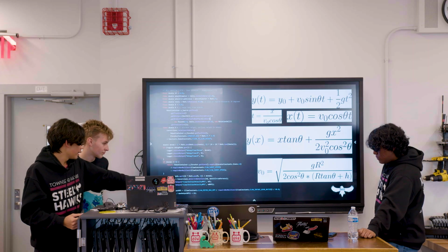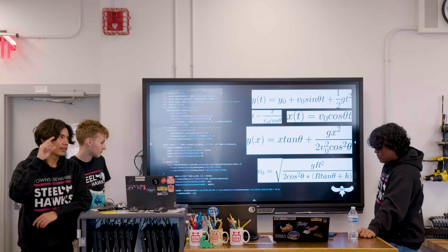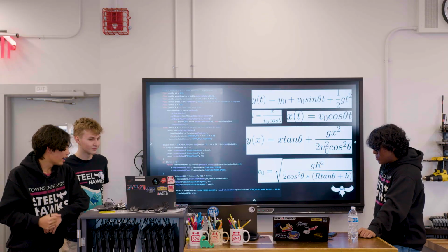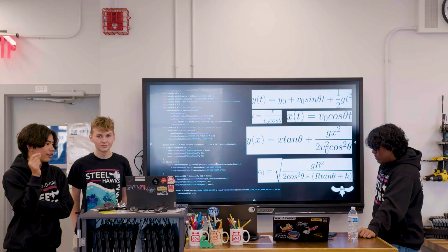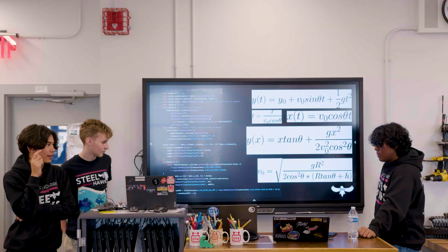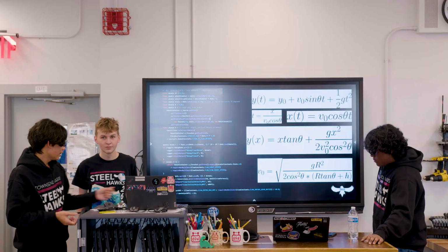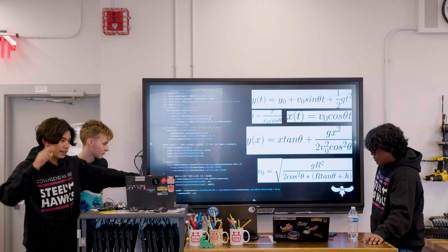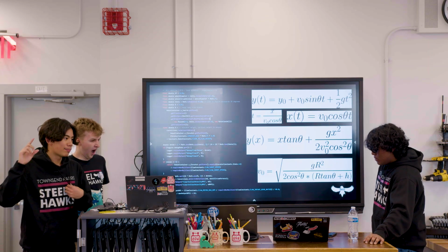And then we log it, and then after that we have the max rotations per second that our claw can move at. And we do this by finding the max RPM of our motor, dividing it by our gear ratio, and then dividing it by 60 to go from rotations per minute to rotations per second. And finally, we return a proportion between our calculated initial velocity and the max output, right? And that's our percentage output.